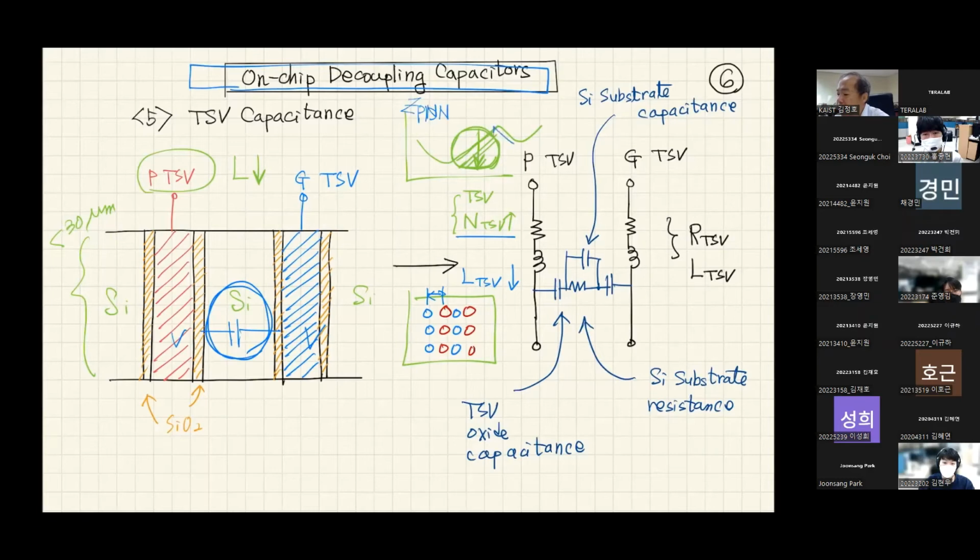So if you are designing this PDN impedance at the chip level or this level, I would suggest including the TSV effect. One of the contributions of TSV is that the inductance will be reduced in this frequency range, and you can increase the capacitance in this frequency range. This inductance is actually mainly from on-chip interconnection, and TSV is helpful in this frequency range. Now, I would like to talk about the decoupling capacitor characteristics, the capacitance component formed by TSV.